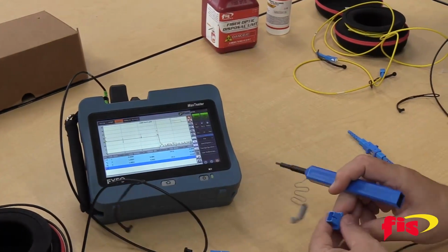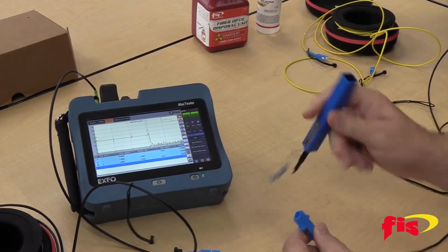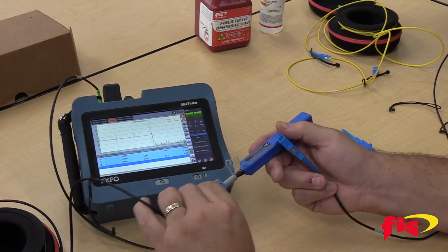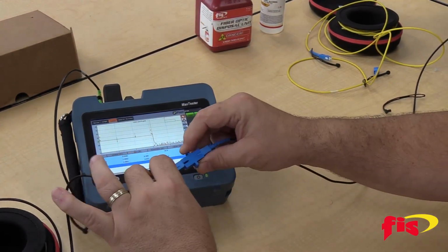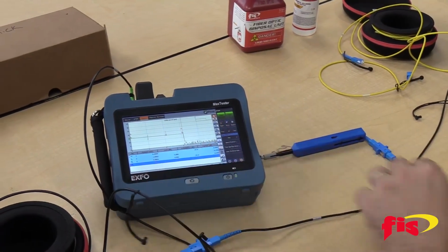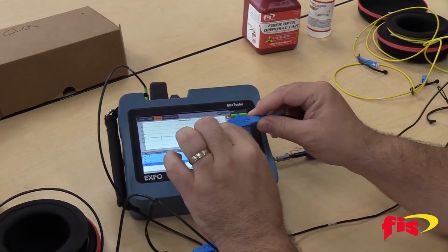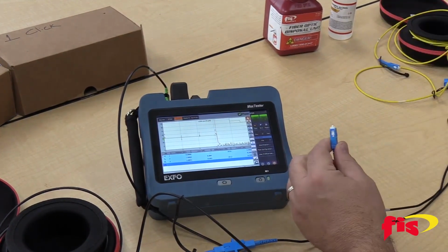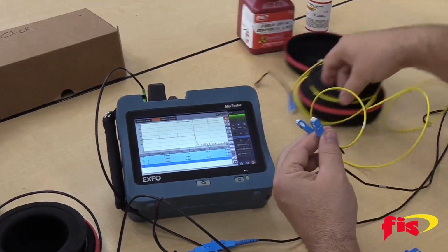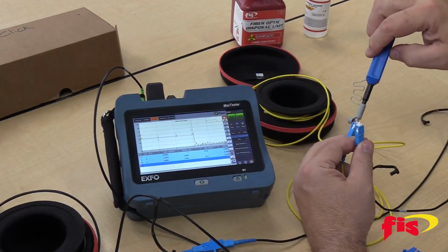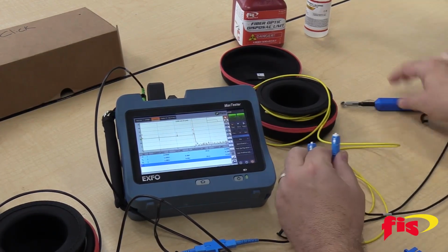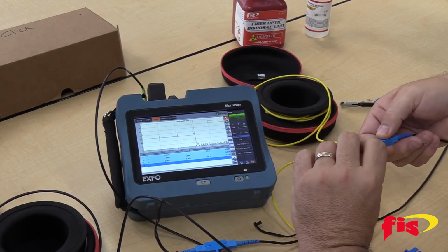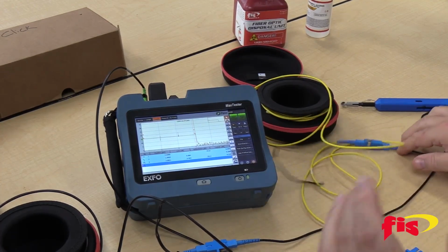And then I'm going to mate this into my test cable. So here we go. Now we have 100 meters in front of my test cable. And now here's the end of my test cable with my terminator. I'm going to take that off, and put a receive cable on the other side. So I have another hockey puck, as you will, and I'm going to clean that and mate those together. So now I have 100 meters plus or minus on each end of my test. So I'm sandwiching in my test.